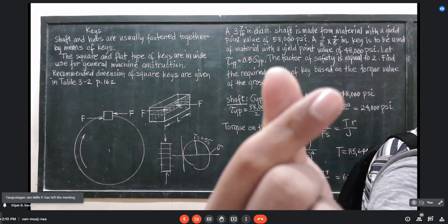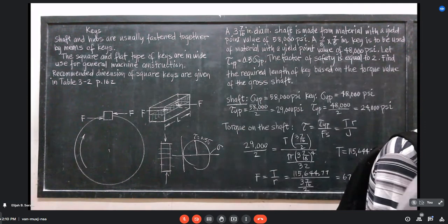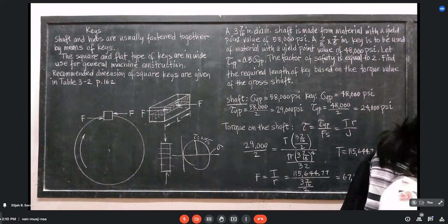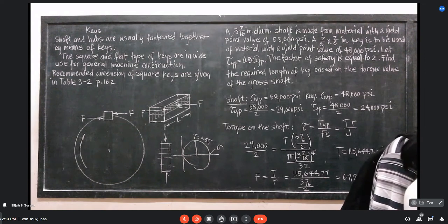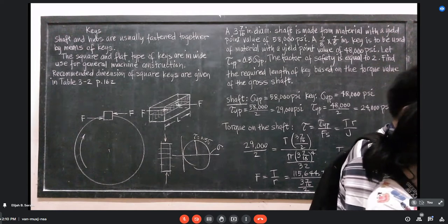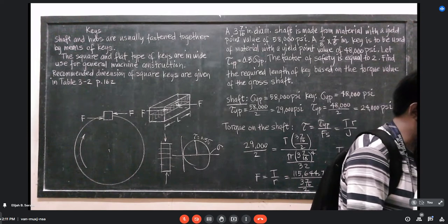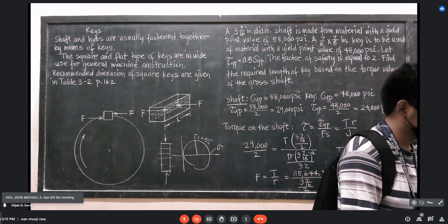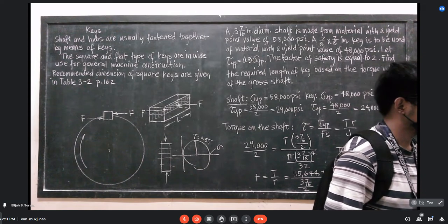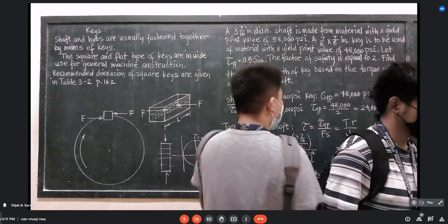Where did you get the center of gravity? Probably your center of gravity is here. It will not be the same, because your center of gravity based on top or bottom is short. So, as for the answer, it doesn't matter whether your basis is on the bottom or on top. It only indicates whether it's from the top or from the bottom. It's still the bending stress, whatever. You only compare what you have.